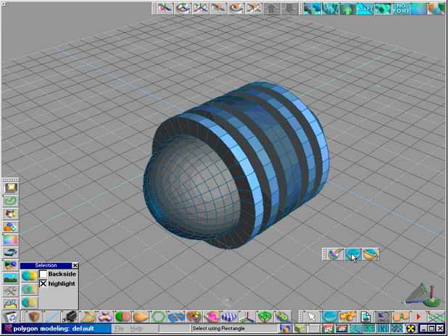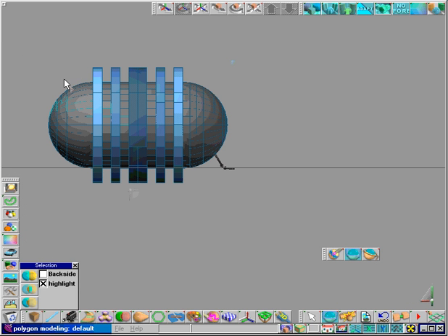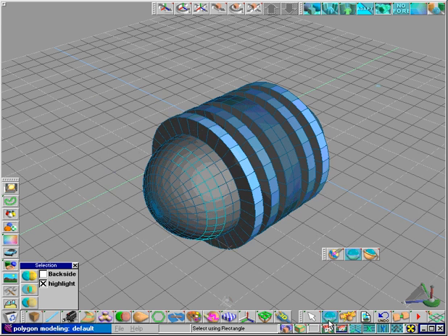The next method is the rectangle selection tool. With a click and drag, we create a selection window. All features contained in the window will be selected. Unlike the freehand selection tool, in its default mode, this tool will create a new selection with each click and drag, undoing the previous one. This method will work in any view, but can be very useful in alternate views, allowing exact selections like this.